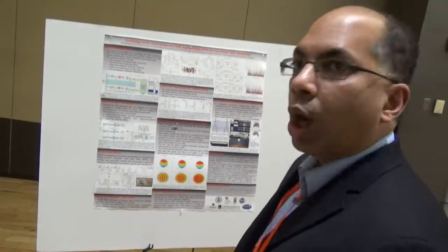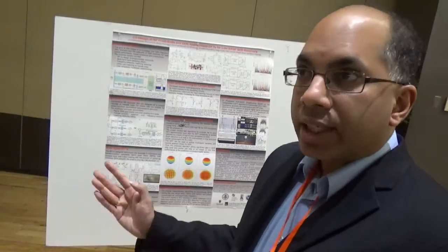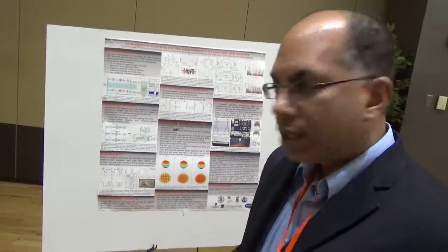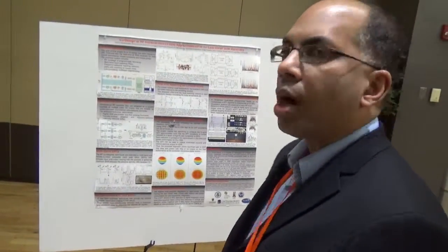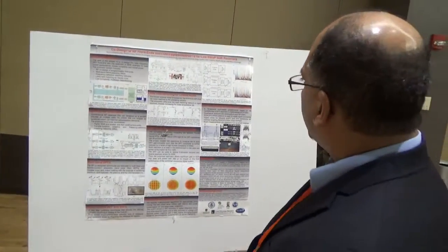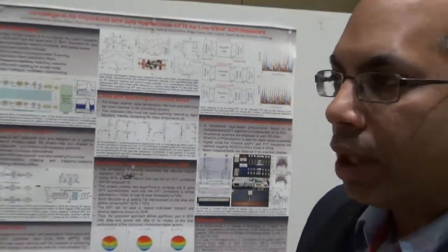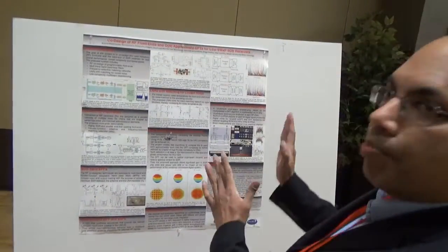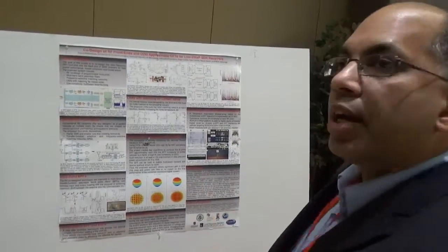For example, for 1024 point transforms, the factor of log n is 10 times. You can make it 10 times smaller. When you make it 10 times smaller, because it's an approximation, the frequency responses of your discrete Fourier transform are not that good. There is some error, some imperfections. So we quantify imperfections. That's the price we pay for getting something that's more than 10 times lower in power consumption.